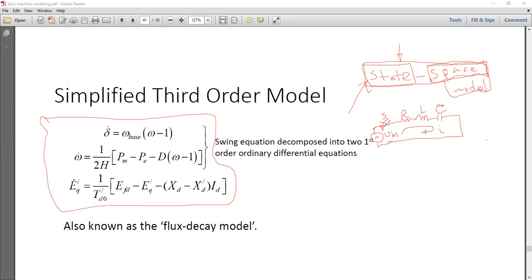Now, once the switch is closed, we have a closed loop. Can you apply KVL here? If we apply KVL, what would we get? V in is my source voltage. Then I multiply the current of the series element by R. Then L di by dt.